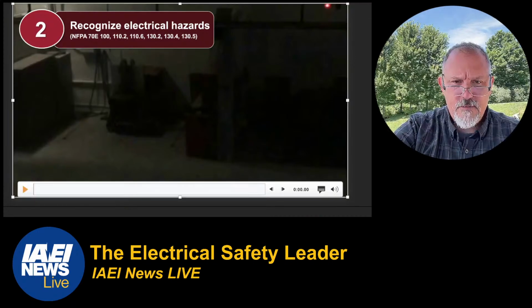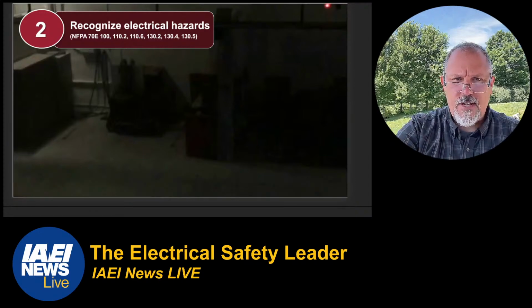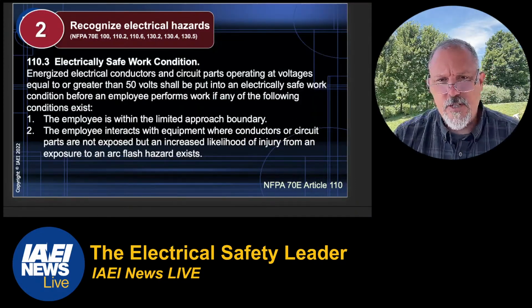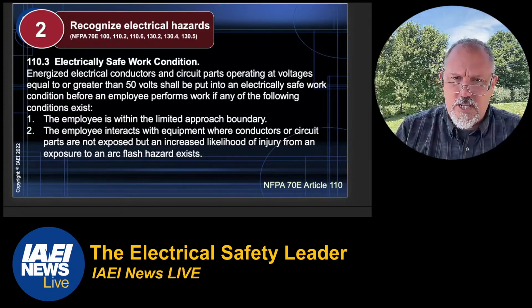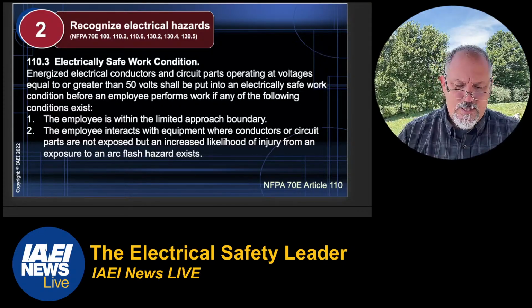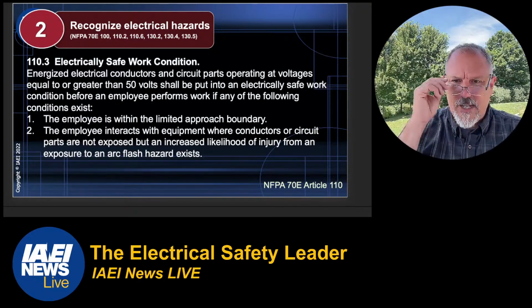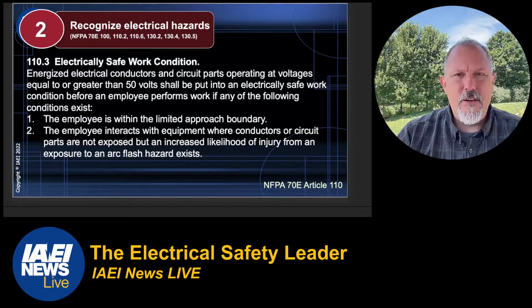Arc flash. You've got to recognize that arc flash events can occur. Electrically safe work condition: electrical conductors and circuit parts operating at voltages equal to or greater than 50 volts. This is 110.3. 50 volts is a threshold. That's a number you need to be aware of.